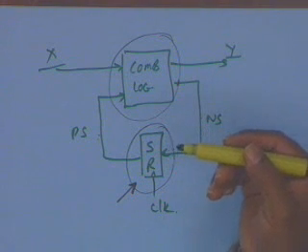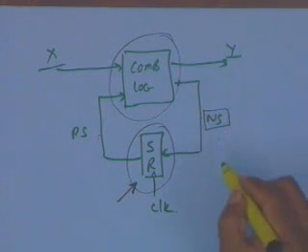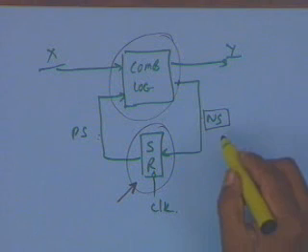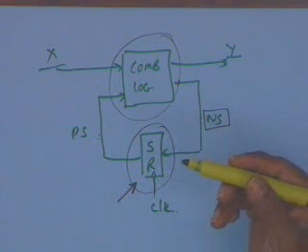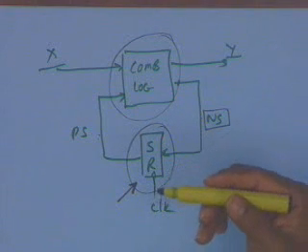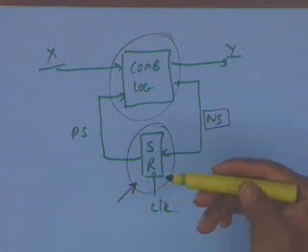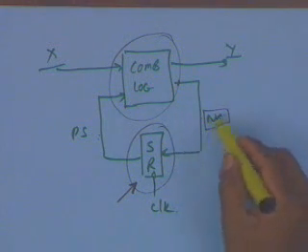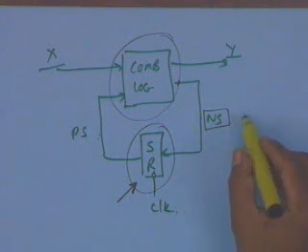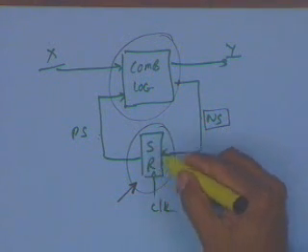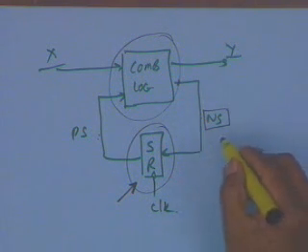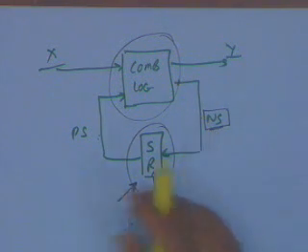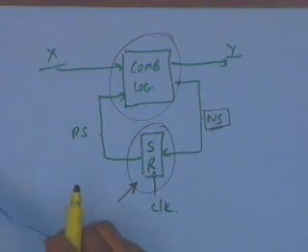But when I am having any other type of flip flop, what I have to generate is not the next state, but the inputs required by which this particular state register will go to the next state. After all, what I want is, in the next clock period, to go to the next state. So whatever excitation inputs are required for this particular set of registers to go to the next state is what is required. And so in that case, I will not directly generate the next state, but generate the excitation inputs.